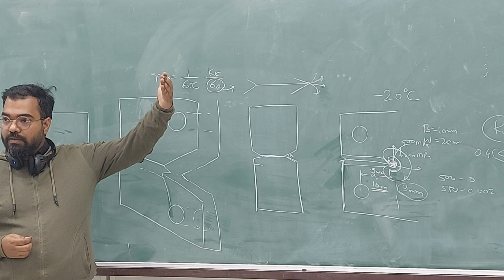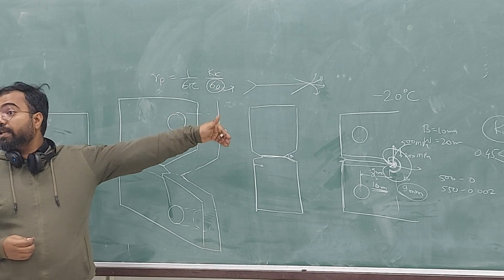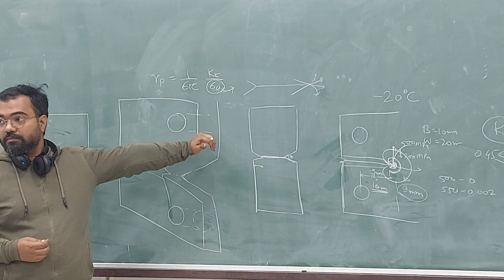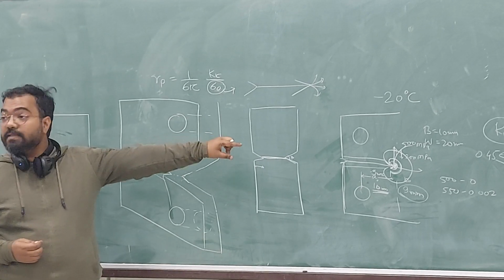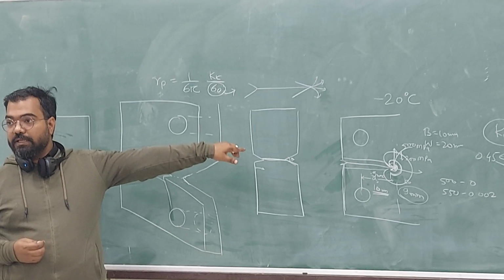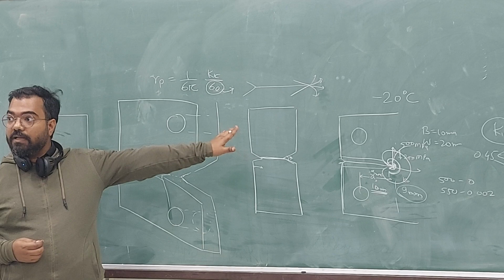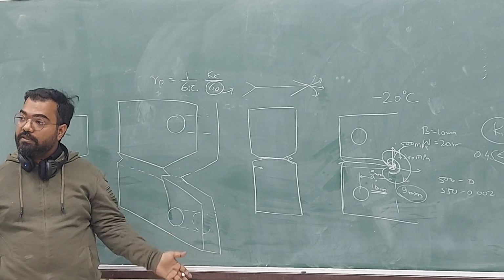If your A by W is very small, if your A by W is less than 0.45, in that case it is under plane stress situation, whatever the thickness is.